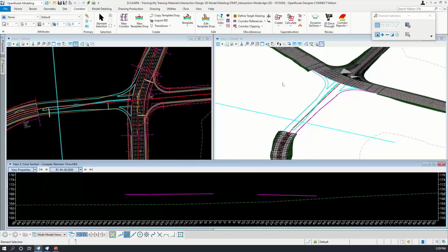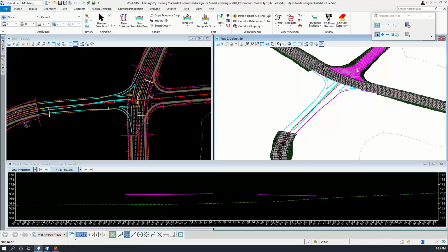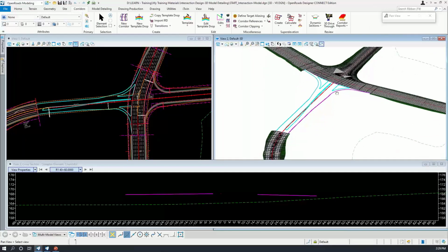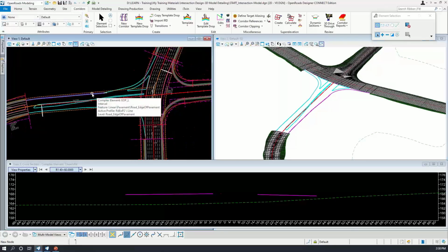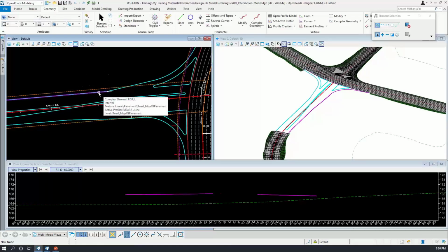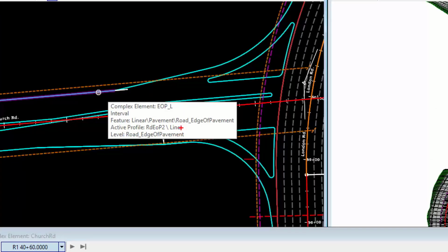to a form in terms of the pavement thickness, and then the cut and fill that will be happening on the ground. Now there's already one on the right side of the road here, but I'll be just focusing on this part here. Okay, now I've already placed some geometries, which are created basically using the geometry tools of the software, horizontal and vertical. As you see here, these geometries already have elevations or profiles assigned to them. As you can see here, there's an active profile already for all these geometries.